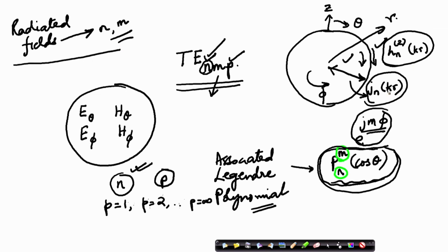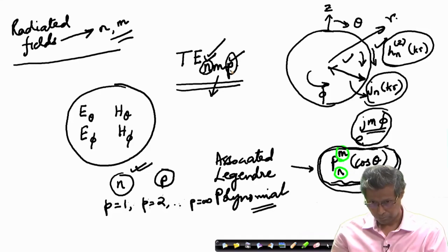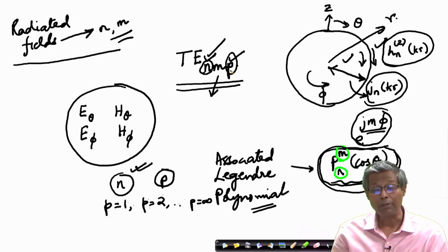But you see here there is nothing called p. So, p is not going to determine the radiated fields, it is only going to determine the resonant frequencies, and therefore, this knowledge of modes, this behavior of the modal indices enables us to design an effective antenna structure.